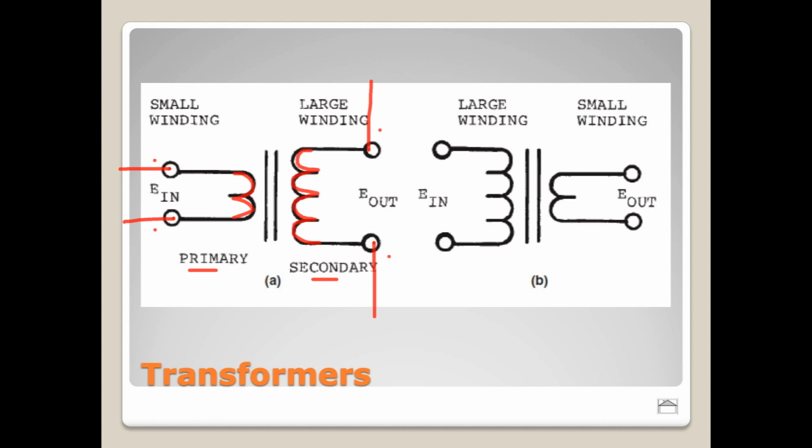The coils of wire. Generally speaking, you're going to find that the schematic symbol tends to approximate the actual turns ratio. So in this case, we see there's 2 coils here and 4 coils here. So my guess would be that this is actually a 1-to-2 transformer or something close to that. Even if it isn't exactly 1-to-2, it might be a 1-to-1.75 or something like that. They tend to approximate the turns ratio. Also notice that there is a couple of lines here. You'll see some variation on this, but there's always going to be something in the middle here to show that there's a core of some sort, right? This is what's carrying the magnetic field between the 2 sides.